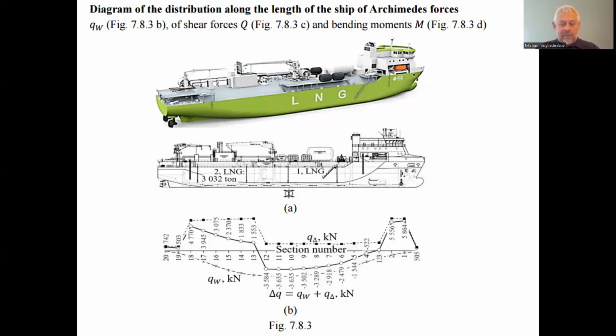So 5.2 meters is a low draft, and to exclude slamming, if we have cargo only in the aft capacity, the ship will have not only the maximal bending moment, but perhaps also a trim to the aft.